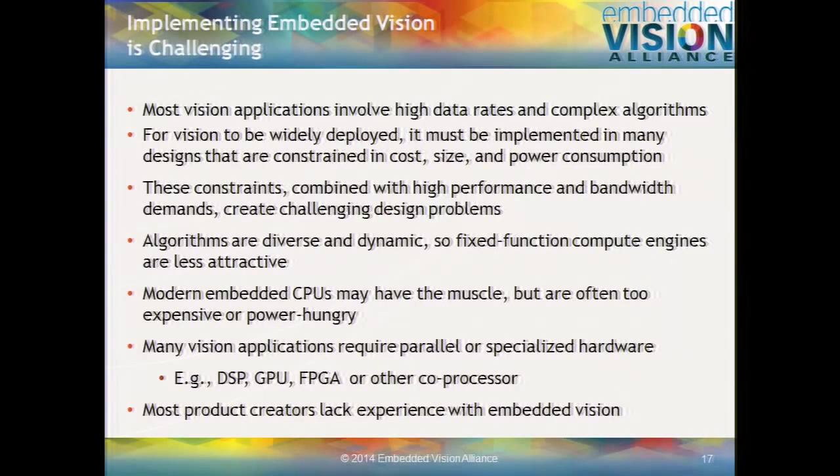Now, in reality, there's a continuum, and often what happens is the front-end steps, things like the image enhancement and 3D stereo depth extraction, which are relatively simple and relatively stable algorithms that people have been using for decades, can and are reduced to fixed function hardware. And later stages, which are less stable, are where it's dangerous to put things into hardware because the algorithms keep changing. And so people rarely do put them into hardware.